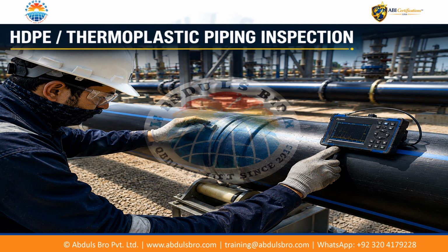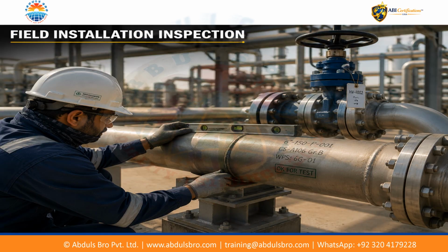the applicable project requirements. Field installation inspection verifies that piping is erected in accordance with the approved drawings, specifications, and design requirements. QA/QC confirms routing, orientation, elevation, slope where applicable, flange alignment, and wall penetrations, and field tie-ins. Pipe supports, anchors, guides, restraints, and spring settings are verified for correct location and installation. Unauthorized supports or field modifications are not accepted without appropriate approval.